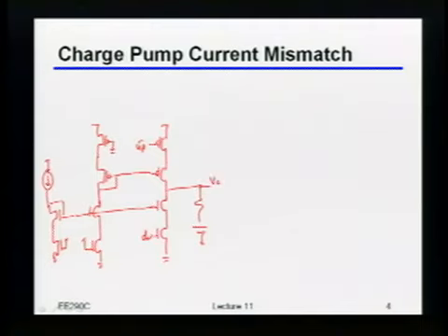Okay, so let's say that you want to build a PLL that has as wide of a frequency tuning range as you can get. What is that going to say about what you're going to want to do with this control voltage? What are you going to do with that? You're going to change a lot. Yeah, you want to be able to move that control voltage as much as possible, right?